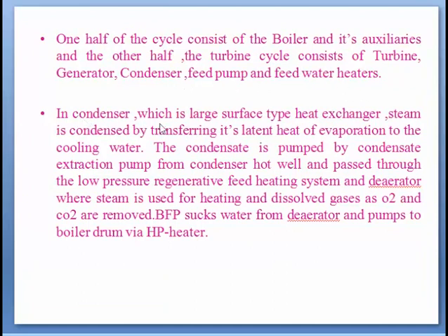The condenser is basically a large surface type heat exchanger, where steam is condensed by transferring its latent heat of evaporation to the cooling water. The condensate is pumped by the condensate extraction pump from the condenser.